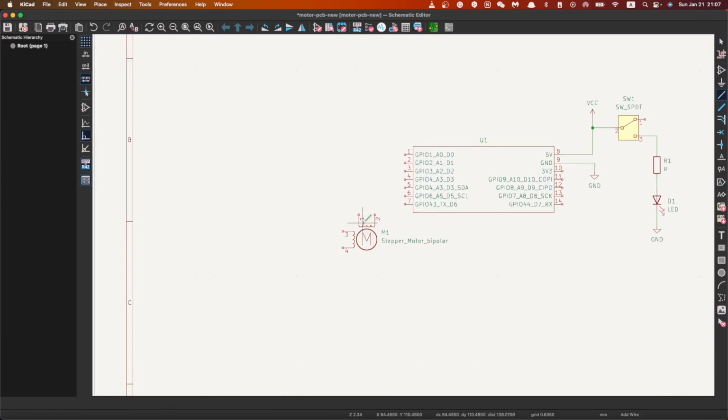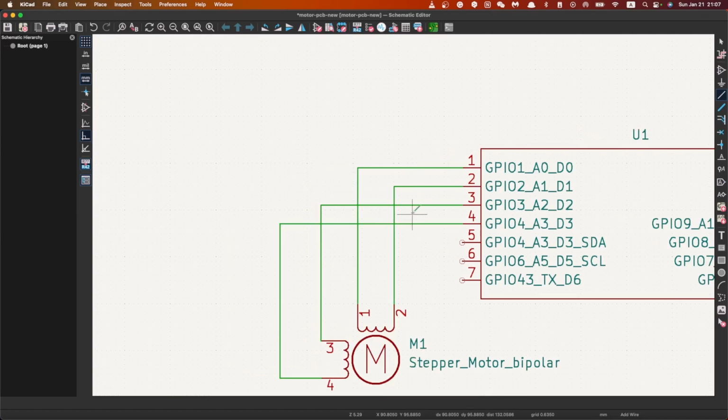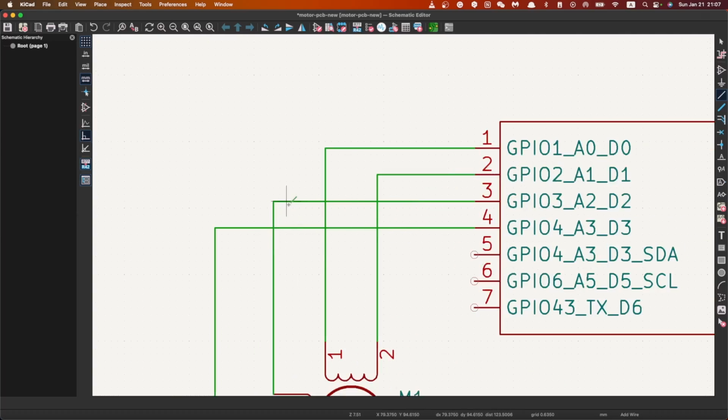And then we can just use this wire to connect them to the analog pins on your MCU. Each time those pins are connected, these circles will disappear. And don't worry if these wires cross each other. As long as there's not a solid circle like this, it means they are not connected like a crossroad. They are being crossed like a bridge, and this wire and this horizontal wire are not connected at all.